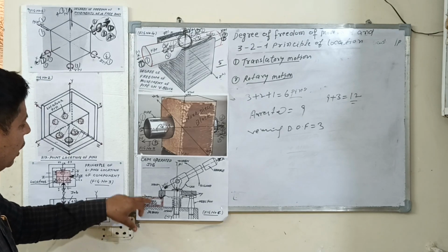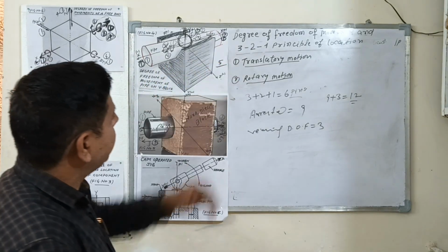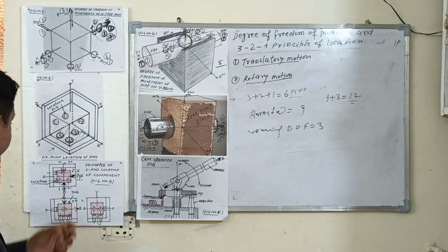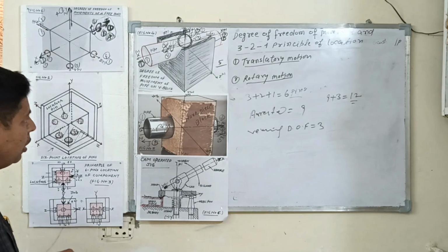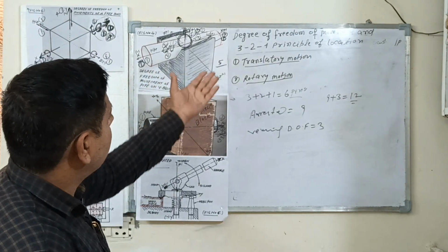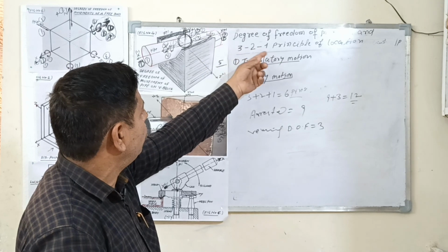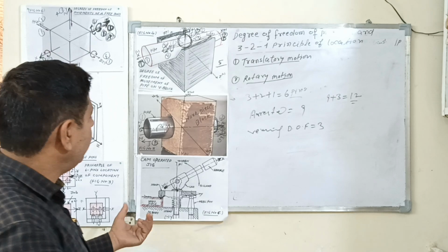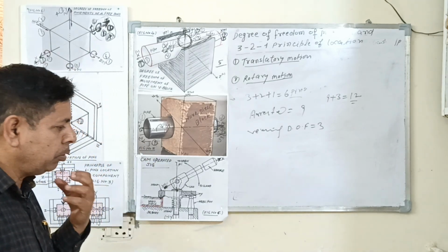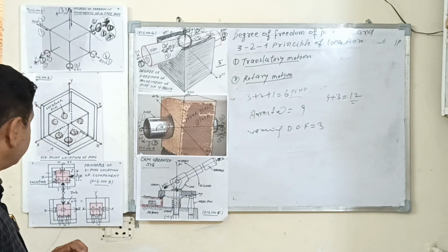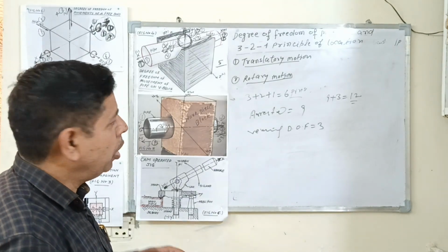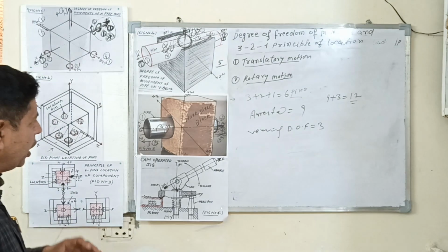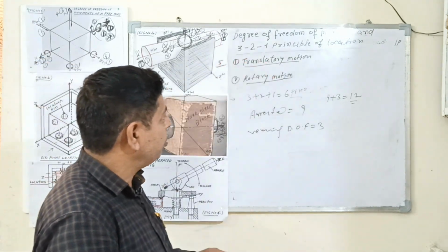on the surface. The 3-2-1 principle of location plays a very important role in controlling the workpiece for finishing the work. The 3-2-1 principle of location is used for foolproof holding of the workpiece and to get high-grade accuracy, and also so that identical parts can be produced with the help of a jig and fixture and the 3-2-1 principle of location.